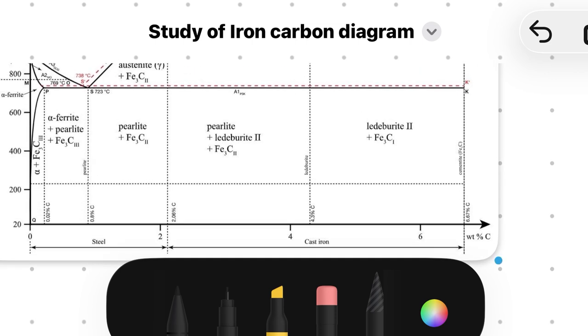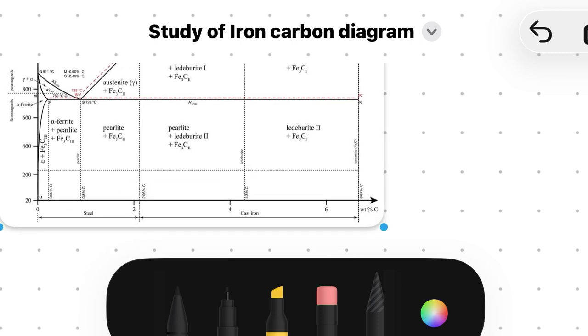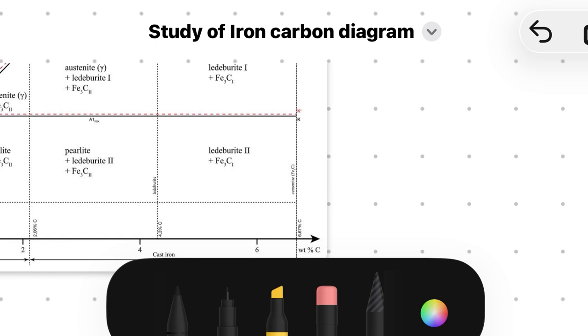In your mind you might think that if the carbon percentage is high, the strength gets higher, but this does not always happen. It is because of factors like the Hall-Petch relationship and the grain orientation. If the grains are smaller and finer in size, the material would have very high strength.